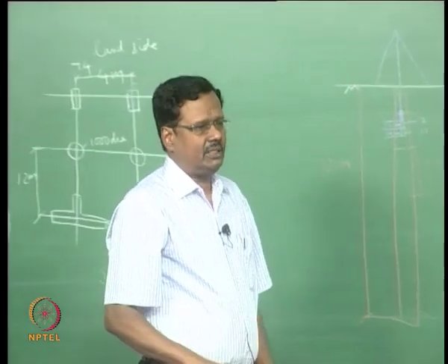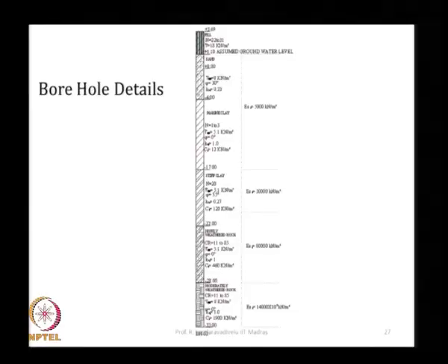So, when we started doing this analysis, we have taken the soil profile exactly at the location of the berth. When we did the soil investigation, top level was 3.69. There was an original ground level at plus 1.1. Above that they used some filling. The filled soil has gamma of 18, and N value from 22 to 31, about 2.5 meters thick. They did 2-3 tests here, each point you will have different results. The range is 22 to 31.